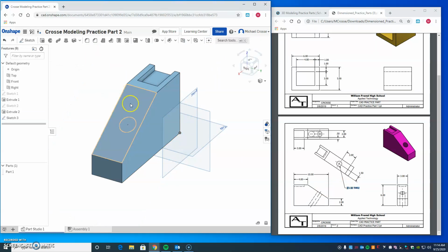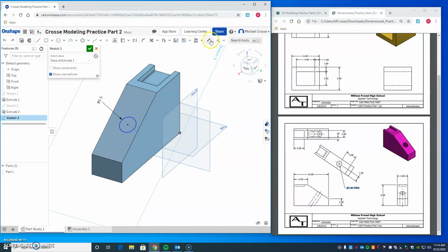I'm going to use that same dimension tool. I have to edit this sketch to specify its location, like where does this hole go? Notice that if I don't specify that, I could even move it. So I haven't nailed that information down. So let's define it.